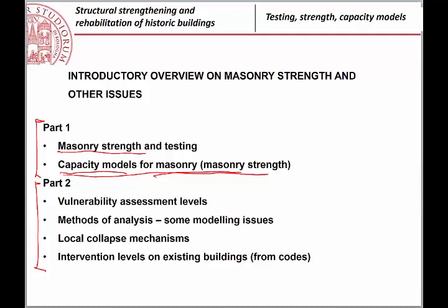A good behavior of a masonry building is when the building is working as a box, but in order to be a box, of course, the walls must be connected together, and there is some interaction between the behavior of the panel in its own plane and the behavior out of plane. But this division between the two behaviors will be much better described in the following.